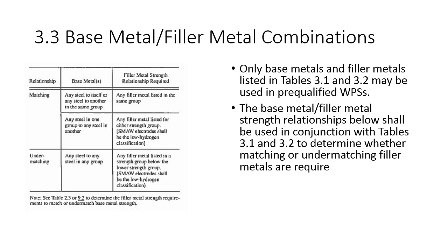If you're welding base metals from a group 1 to a group 2 or a group 2 to a group 3 or whatever you've got going on, this will help you figure out what you need to do as far as getting your filler metal strength straightened out, and then finding which filler metal is proper to use and if it even fits in with this code or this clause. Maybe if the filler metal you want to use for certain base metals doesn't fit in with tables 3.1 and 3.2, you might have to just qualify the procedure and go to Clause 4.